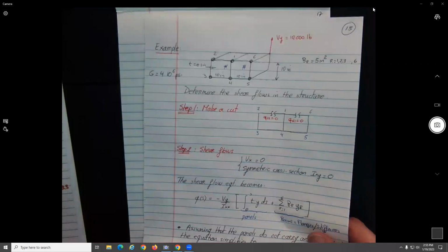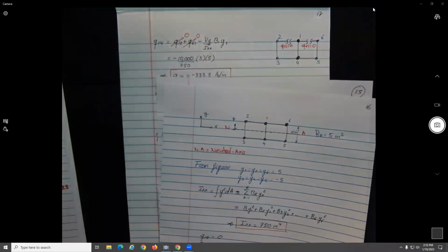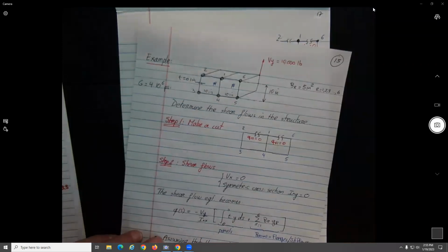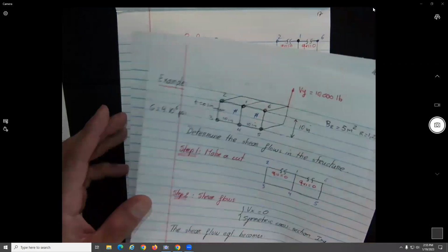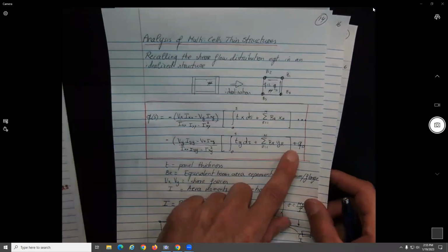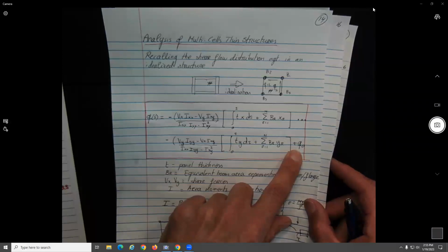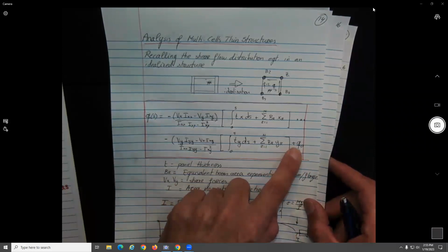Okay. So now, something I did not mention is that here, what is my page? Let's see, first page here. Here we made the cuts. But because we made the cuts, I did not put it here in the equation. What's happening over here when you have a closed cross section? You have inside some type of initial or residual shear flow, no? That we're going to have to calculate because it's not zero. The cut is not there, so there's some. This should replace the cuts. Okay.